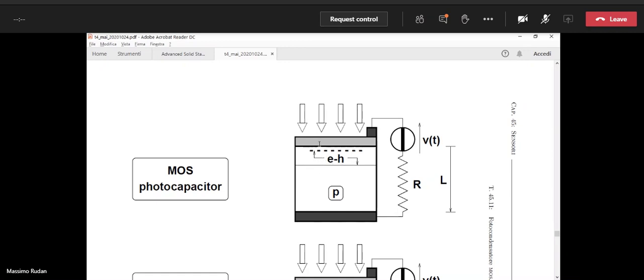It happens that since we are applying a positive voltage on the gate, the holes that are also positive are pushed away from the surface. And here the dielectric relaxation time comes into the game, because the dielectric relaxation time is the typical time that it takes to the holes to being pushed away, so that we form a depleted region, okay?